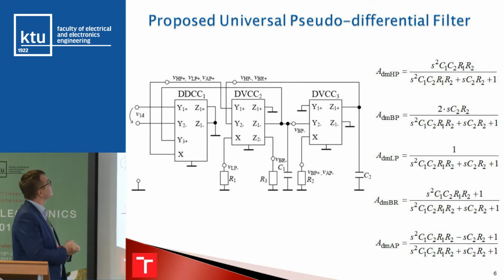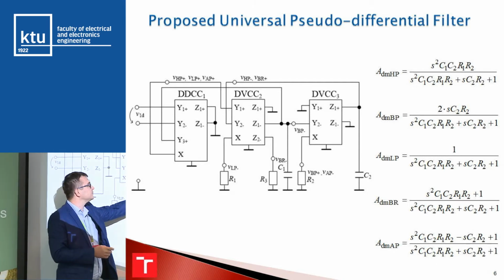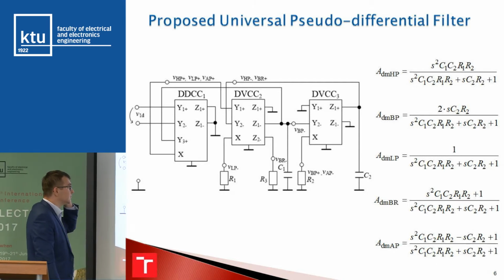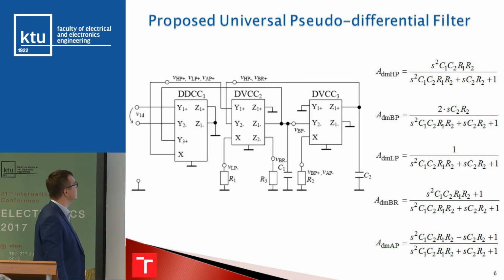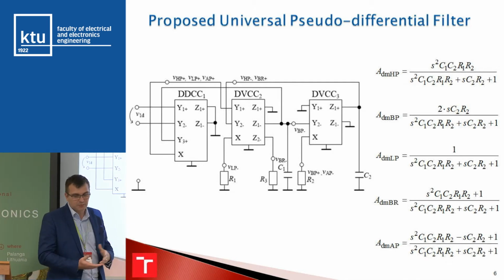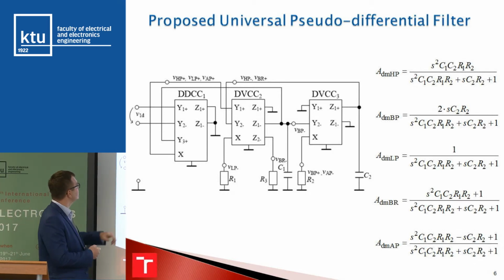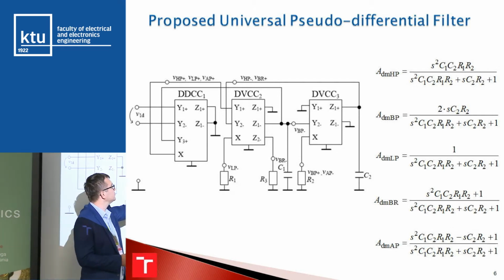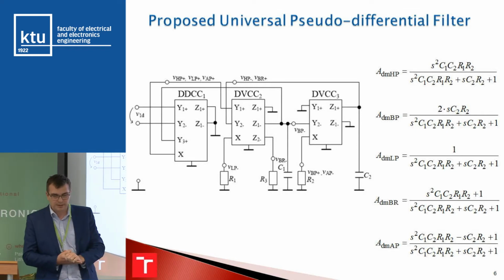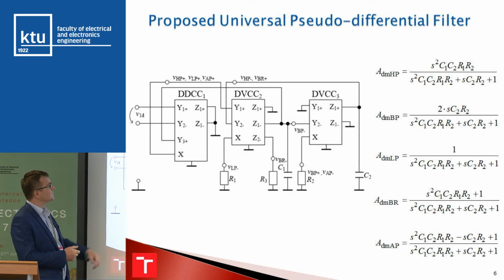Here we have the final solution, where we can see the core of the frequency filter, and it is just a simple single-ended structure. There is no differential operation observable just from that, but by feeding the circuit in an appropriate way, obtaining different responses and taking the difference between them, we are able to obtain various transfer functions.